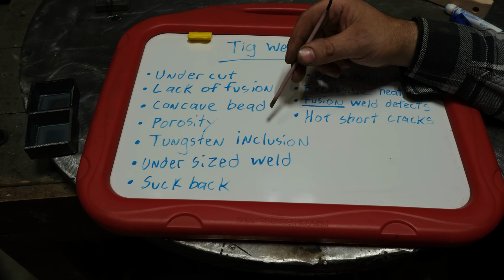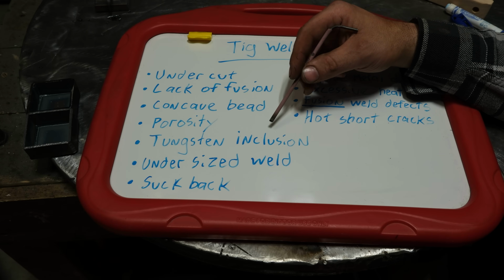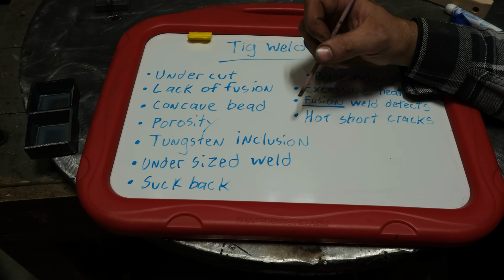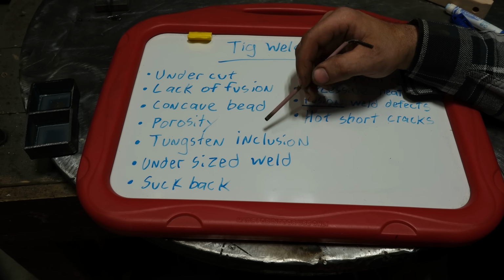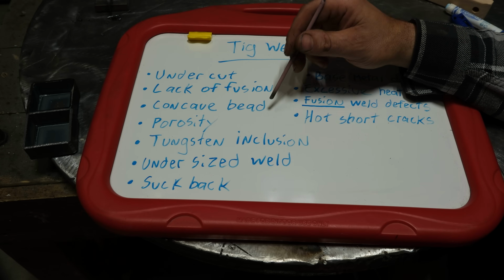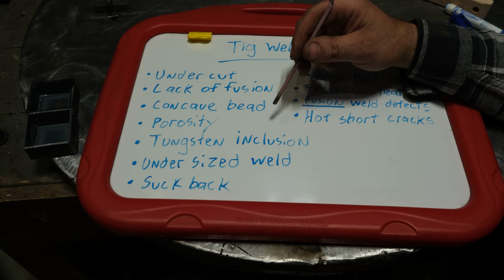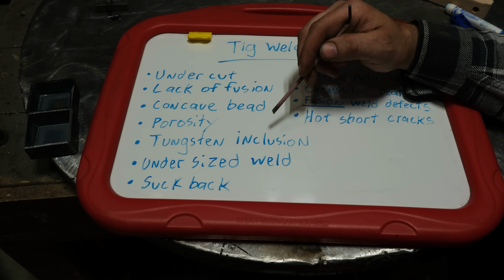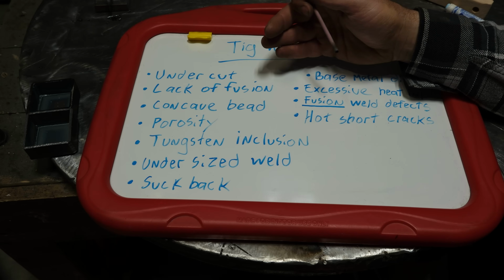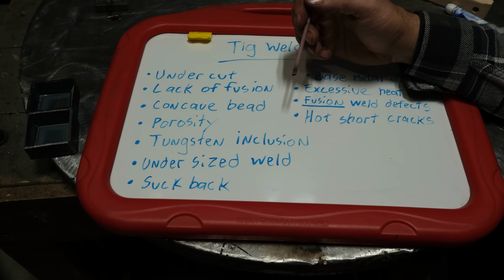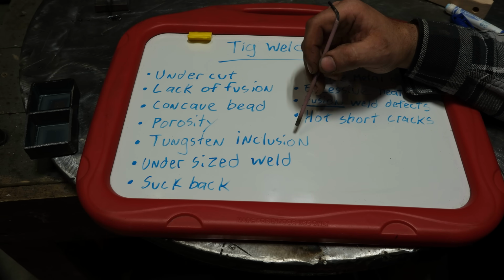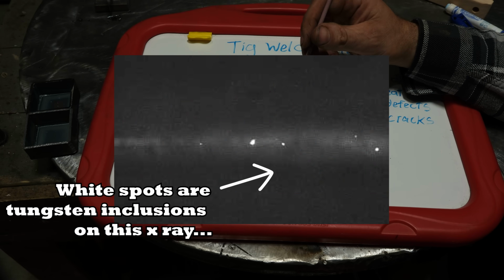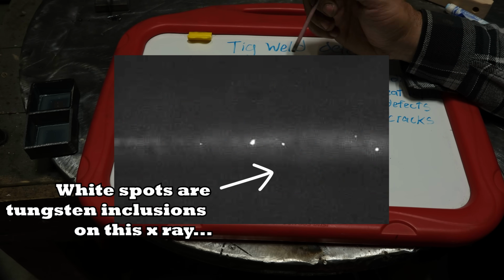If you're building 2000 PSI piping in a power plant, absolutely it could be. The inclusion, much like a pore, is a weak spot, and you could have a failure. A crack could propagate from there, and that is undesirable to leave in there. So in the case of high liability stuff that's x-rayed with TIG welding, they will go and x-ray that pipe, and an inclusion will show up as a higher density spot.